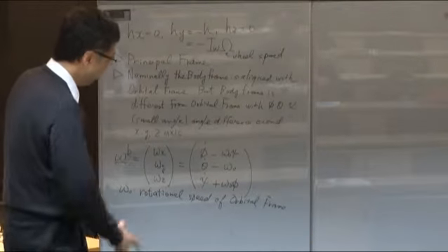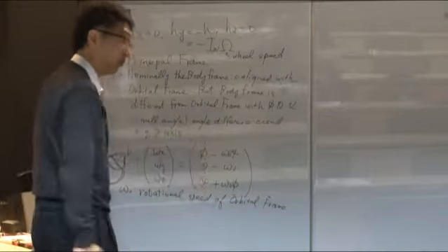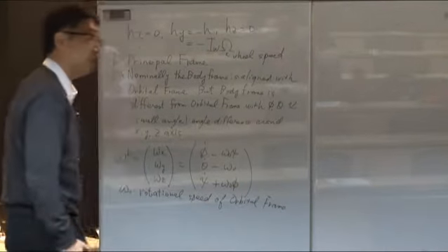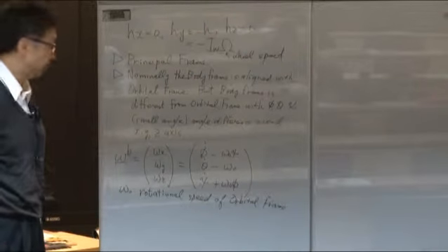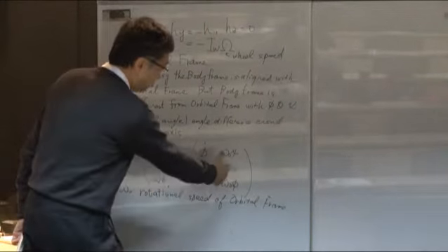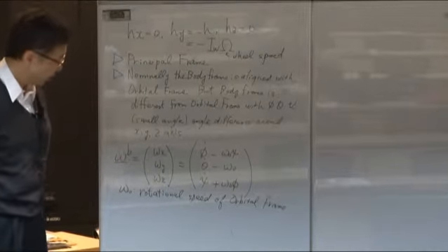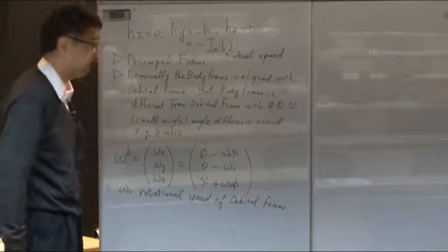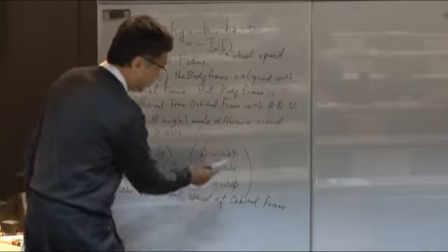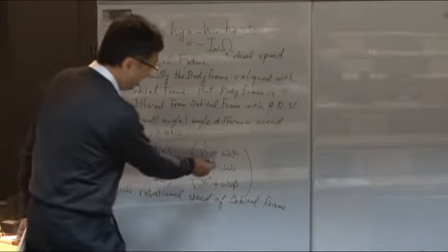So in the y-axis it is minus omega 0 plus theta dot. Theta dot is the rotational speed of the body frame with respect to the orbital frame. These two summed are the body frame velocity. The y-axis is very simple, but for the x and z axes, omega 0 makes a coupling between these two axes.